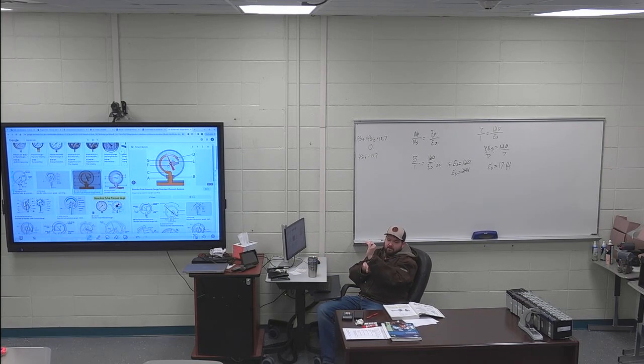As I push pressure in the bottom of this, what's that C going to want to do? Go up. Straighten out. And if I put a crazy amount of pressure in there, it's going to want to open, right? So as the free part of this moves upward, there's a linkage to a gear system that turns the dial.